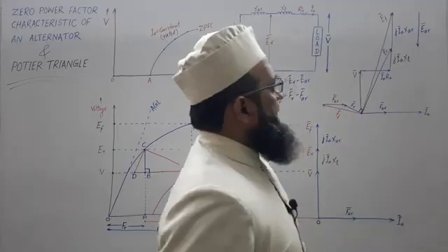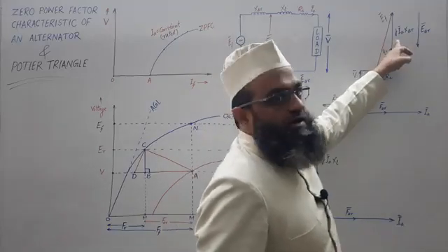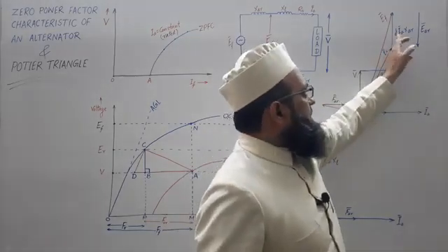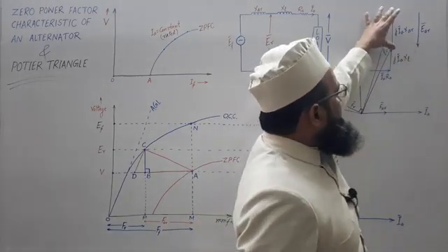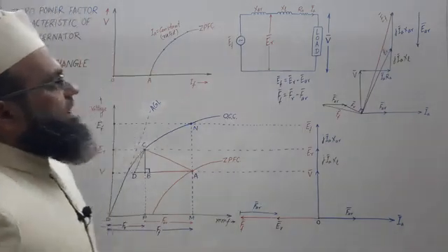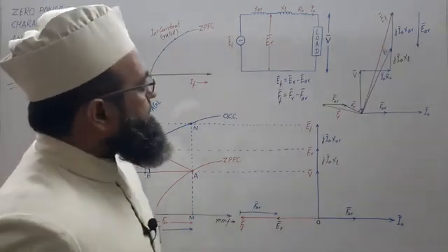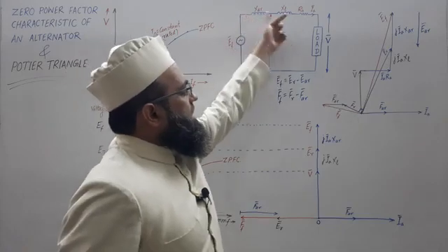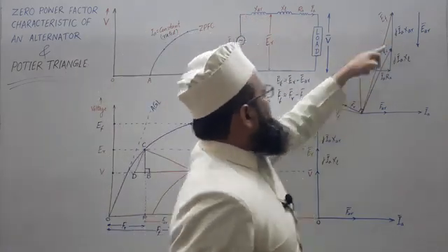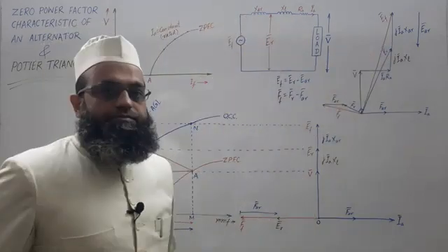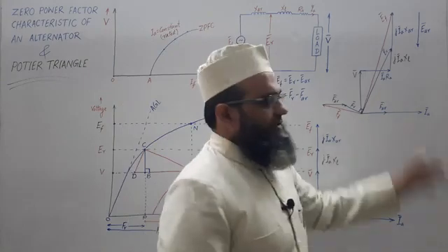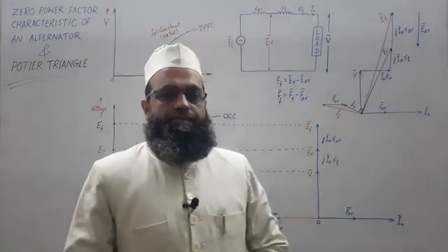If we further add jIAXAR, if IA is this, then jIA will be this, and IAXAR will give the magnitude of EAR, the armature reaction drop, this, and finally the resultant of this will be EF, that is this phasor. EF is no load EMF.